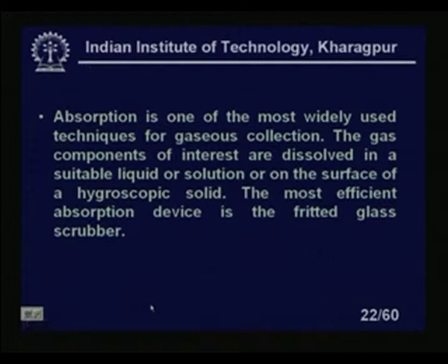Absorption is one of the most widely used techniques for gas collection. The gas components of interest are dissolved in a suitable liquid or solution, or on the surface of a hygroscopic solid. The most efficient absorption device is a fritted glass scrubber, where it can be collected.